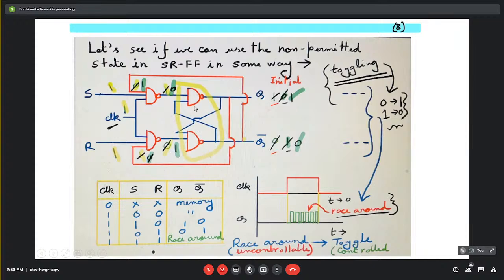This is a NAND gate based latch, so when it is 1 and 0, in the output we will get 0 and 1. So during the enabling period of the clock, it has changed its state from the previous one, that is 1 to 0, and here from 0 to 1. That is, the output has become just the complement of its previous state.